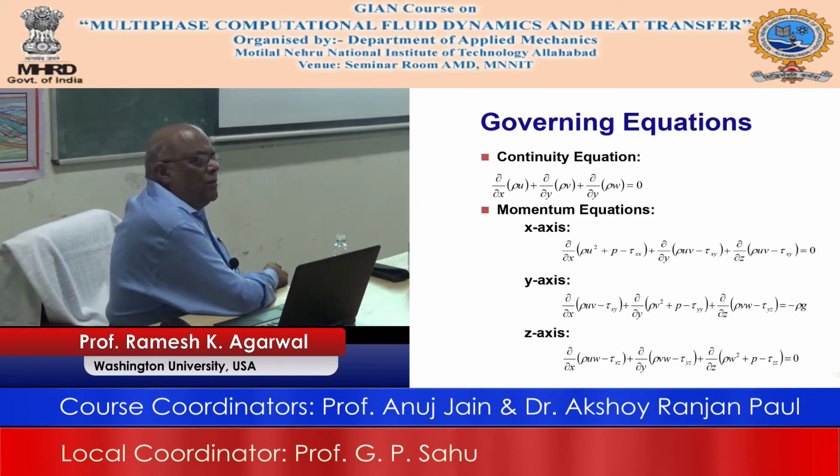So the SIMPLE algorithm. The main SIMPLE algorithm is the Patankar-Spalding algorithm, and that was a major breakthrough actually to provide a pressure velocity coupling. Pressure velocity coupling is nothing but calculating the momentum equation, and from there you get the pressure correction and put the pressure correction into the continuity equation to get a Poisson equation, and then solve the Poisson equation by relaxation. So that is the basic gist of the Patankar-Spalding algorithm.